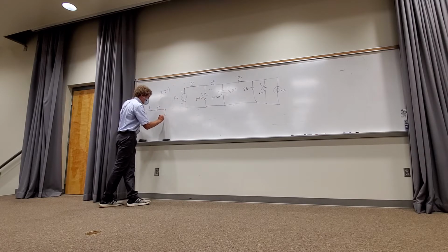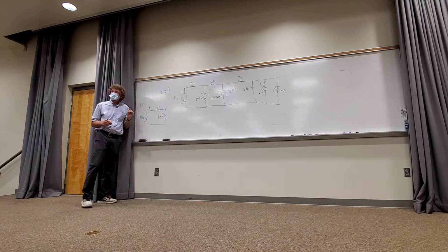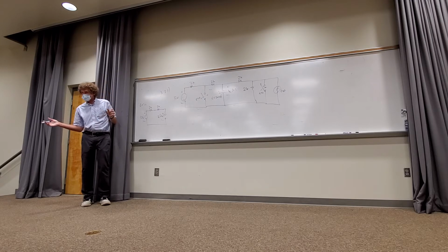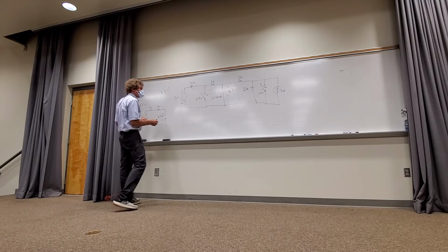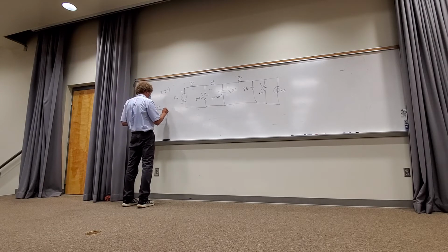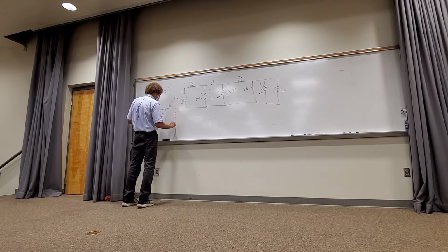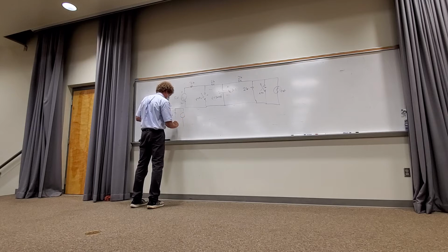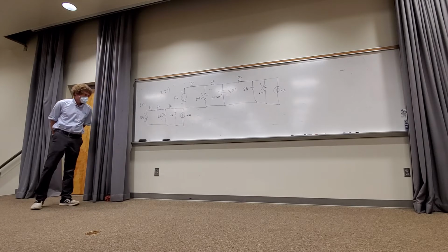Now, I'm going to show the capacitor as just an open circuit so you can better appreciate what really is there for T less than 0. You literally take the capacitor out. Y'all follow me? It's just an open circuit. You're looking for that voltage across that open circuit. Then you have 2K, 2K, and is it 2 milliamps, right? In the problem? So this is what the circuit looks like for t less than 0.